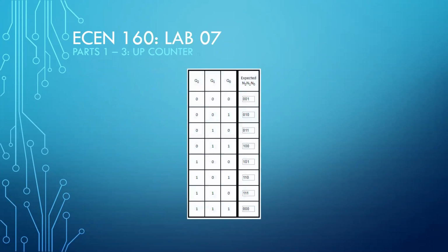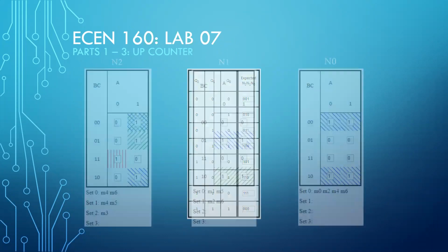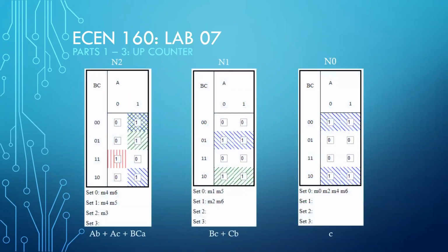We started out with a simple transition table, showing what each output is expected to be on its next transition cycle. Afterwards, we converted the transition table into K-maps, leading to a simplified Boolean expression. This enabled us to make our circuit in Logisim.